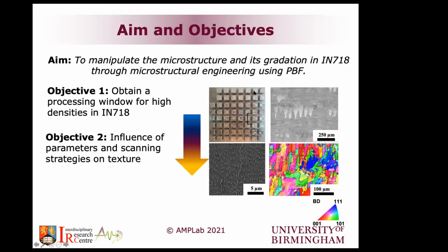So you look into all these samples that you see in front of you, all of them are dense, all of them don't have much porosity. You're talking about 99.9% and more of nominal density. And they are fine, no cracks, don't see much keyholing or anything like that.